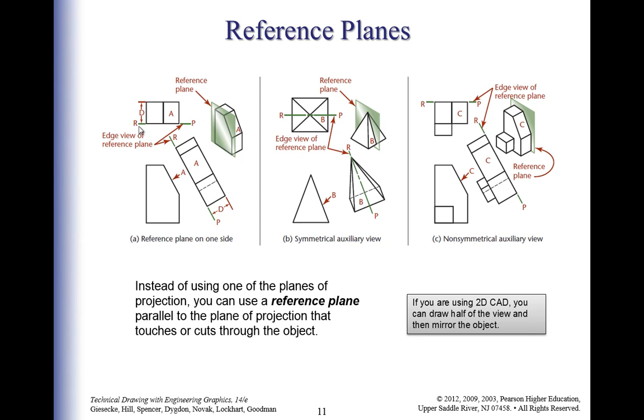So the thing they did was they just made a reference plane from there to there, and they come over here. You put a line in there, and it's not like what we did before with the fold plane line method. You don't have to get your distances correct and all that. All you do is just slap that line in there, and of course this is your primary auxiliary line, so this reference plane has to be parallel with this.